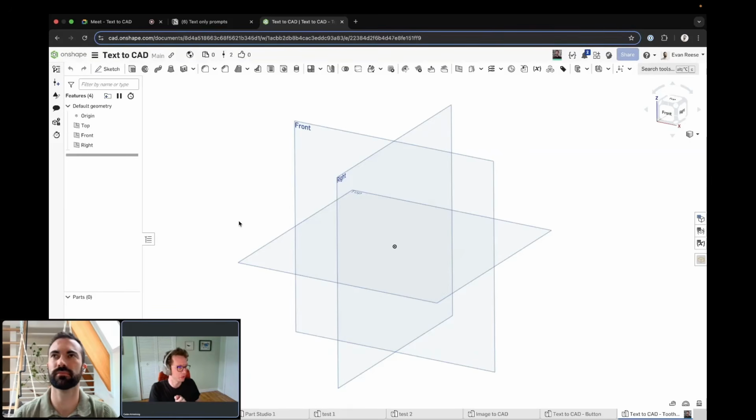The base is 75 millimeters wide, or sorry, 75 millimeters deep, and then 150 millimeters wide. The material is 20 millimeters thick. Sorry, I was talking over you. I'll listen to the full thing and then start cranking. All right. So 75 millimeters by what now? 75 by 150, and it's 20 millimeters thick. Okay. The front edge of the base has a bit of a draft to it, just a slight draft angle.